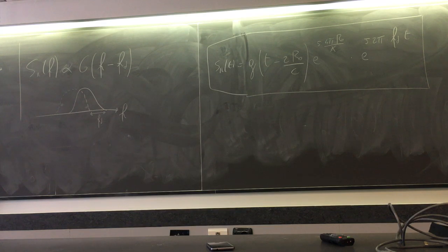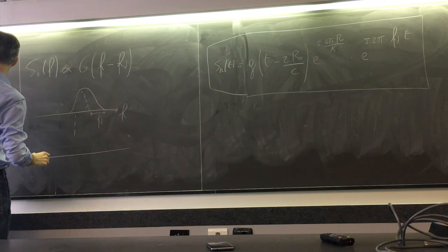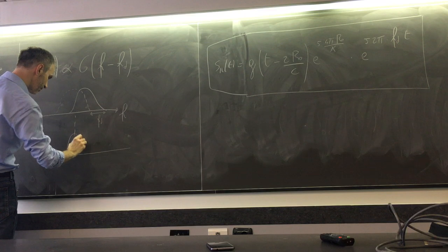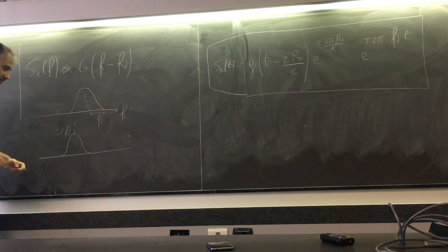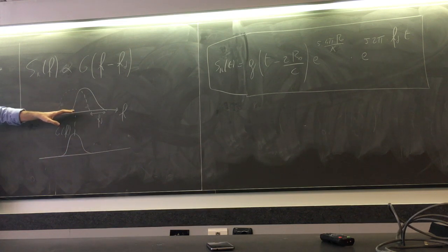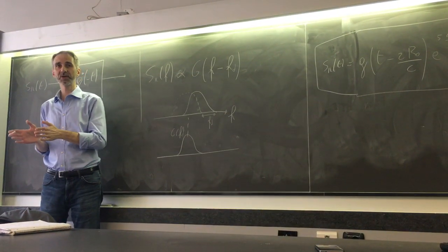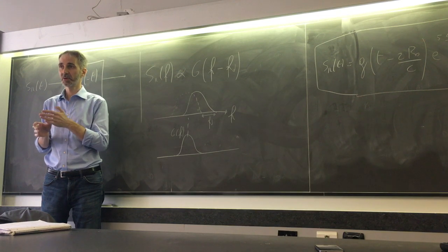Of course, when you are doing your matched filtering, you are again letting this signal be filtered by the same G of F. And so you see that in the frequency domain, your filter is no longer aligned to your signal.